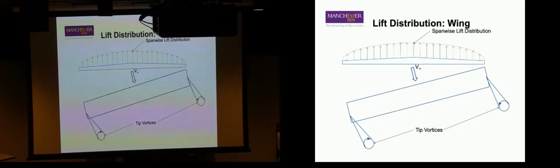So we want that shape to be as close to a perfect ellipse as possible. And actually a very eccentric ellipse, broad. If it's circular, very steep, much more losses. Okay? And we do lots of things to control that. We taper our wing. We increase our aspect ratio. We have wing tips and the like that do that.